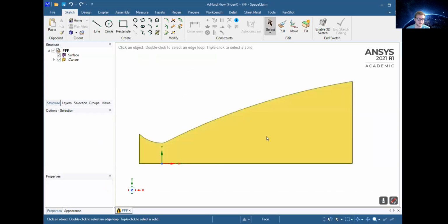All right, so this is going to be our geometry. This is about half of the bell nozzle, and we're going to finish the rest of it using the symmetry tool to do the whole bell nozzle itself. But this makes our lives a little easier by doing half at a time and still getting the data for the full contours and velocities along the streamline, which we can measure right here at the symmetry.